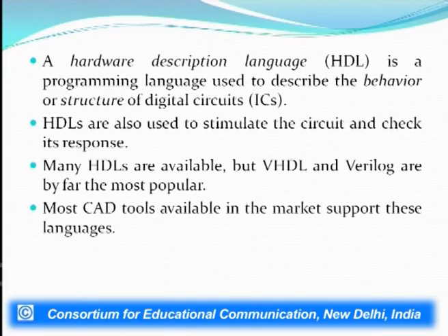This is where the hardware description languages come into the picture. As the name suggests, a hardware description language is a language designed to describe a hardware being designed. Here we are talking specifically about digital circuits and to what level of abstraction we can go, which we will see as we move further into our presentation for the day. Hardware description languages are essentially programming languages used to describe the behavior or the structure of a digital circuit. HDLs are also used to simulate the circuit and check its response.